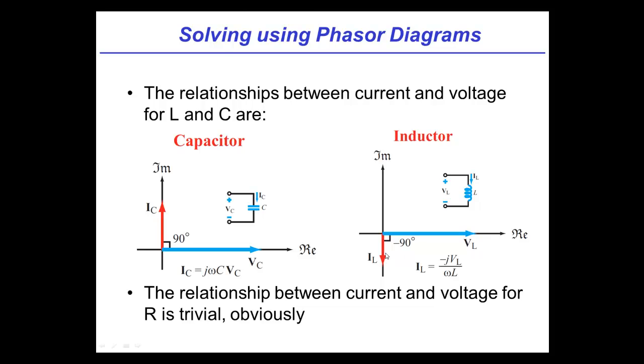Now, okay, big deal, right? So what's the use of this? Well, before we move on, I've got to try resistors. What do you think a resistor is? I think a resistor will have a V and an I, and if the V is purely real, they will line up with each other. Yeah, if V is purely real, lo and behold, the I is purely real. If V is perfectly imaginary, lo and behold, I is perfectly imaginary.